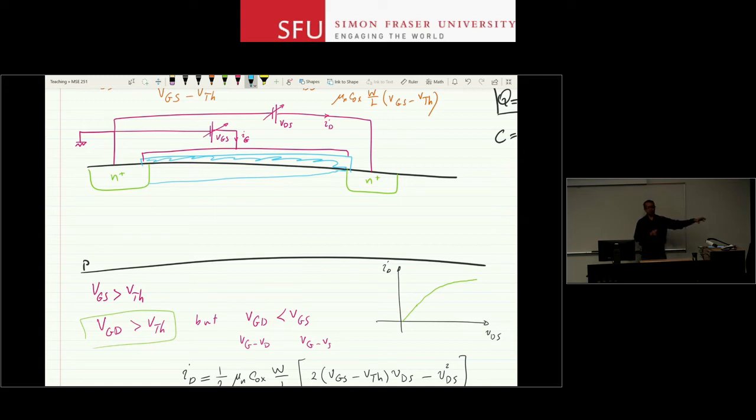From your source all the way to the very near of the drain end, you have a channel, you have a resistor. You bring all the carriers all the way to the edge of the drain, and then at the drain corner, the channel has vanished. That channel has pinched off. But all those carriers that have got themselves to that corner are so close that they just jump over and then they appear in the drain terminal. Well, similar thing happened for BJTs, and now we have a current source, right?